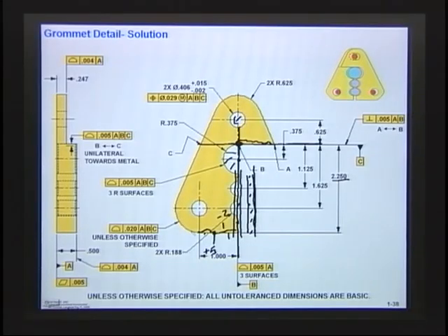See that outside radius? They could come over and set their 0 on the basic dimensions. See that 1.625? They're going to come over that 1 inch to that spot. Then they could come in and probe where this surface is. If they want to find out where this surface is, they could do the same thing. Set their 0 over here and then probe that surface. Right? That's how they're going to be looking at it. So the profile tolerances are just seeing how much it's off its spot. Right? All right, that gives you a little idea, a little insight into the inspection.